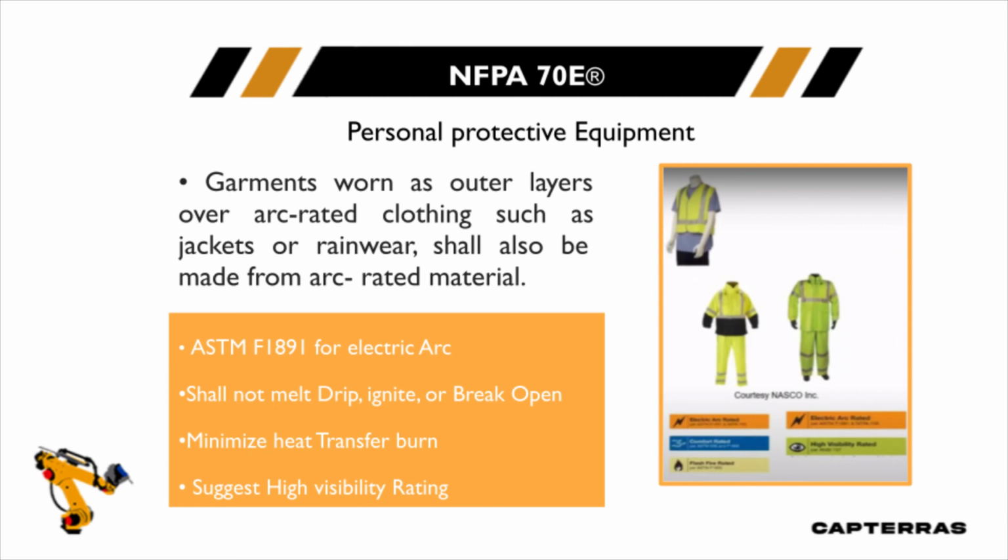But the high-vis vest is made of such a material that it will not continue to burn and melt and drip all over your body. It may after an arc. So in other words, a standard nylon polyester vest will probably catch on fire and be melting and burning over the top of your shirt. Your arc-rated shirt was never designed to protect you against that. It's designed for the short-term arc. So let's not compromise our system by wearing non-arc-rated clothing.